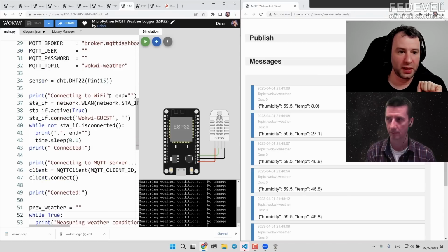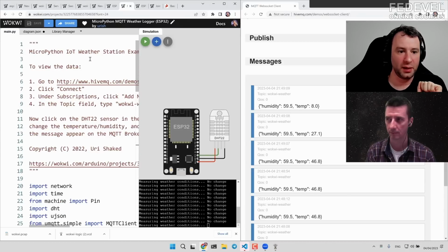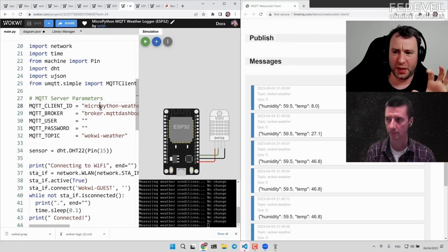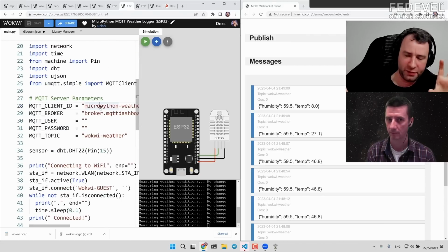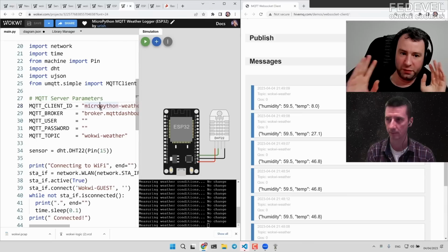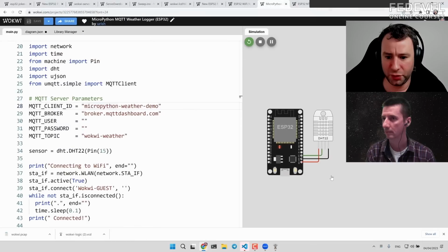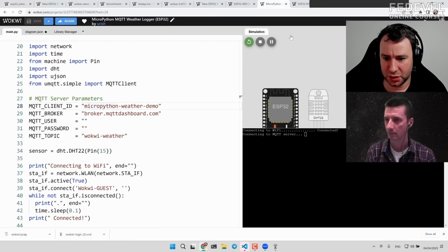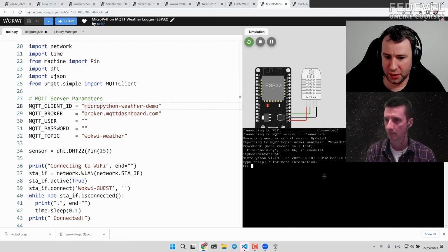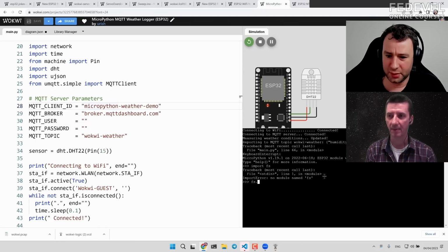behind the scenes, what happens is this MicroPython code is actually written into a virtual file system on the flash. I think we can probably see it if we just Control C and get into the MicroPython prompt, because there must be something already running on the ESP32.